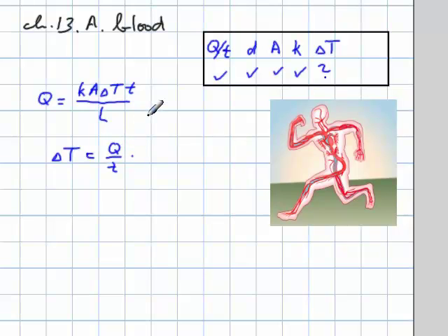This one here is one number given as 240 joules per second, and then times the L or the D, and then divide that by K and A, the D being 0.002 meters, the K being given in a table in the book, let's see, other materials, as 0.20 joules per second meters and Celsius degrees, and the A given in the book as 1.6 square meters.